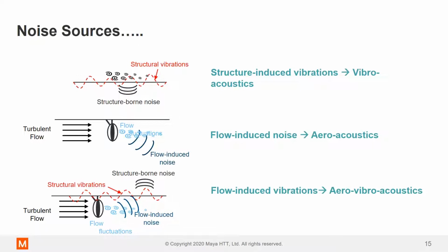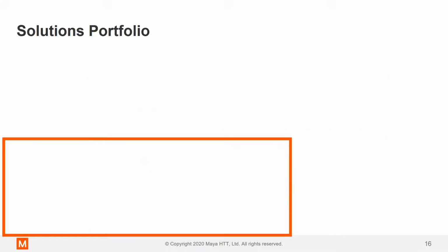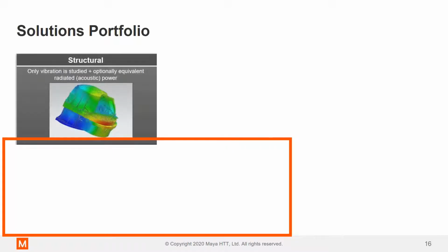Okay, so let's now identify the different simulation tools available to resolve acoustic problems from a physics perspective. Firstly, let's start with a pure structure analysis involving only a structural FEM model. That's a pure structural analysis. We have Simcenter Nastran to resolve such simulations. Now think of vibrations on a gearbox due to excitation on bearing locations coming from the shaft in the gearbox.